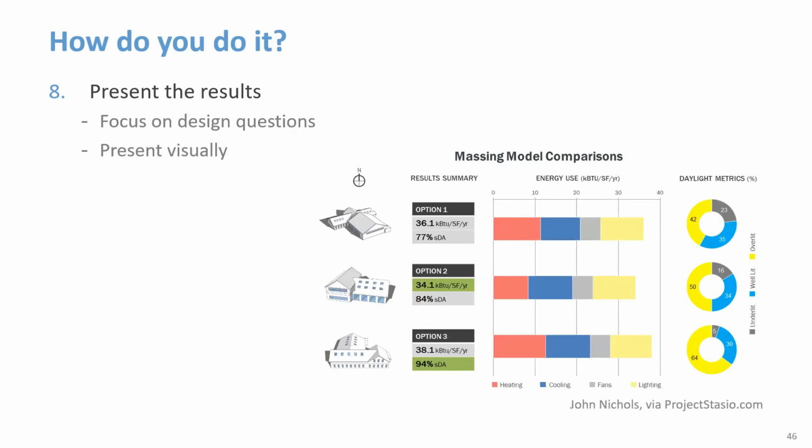The next to the last step is presenting the results of the analysis. When presenting results to owners and design teams, here are 2 recommendations. First, focus on answering design questions rather than on presenting simulation results. And second, present the information visually. Energy modeling results have little value if decision makers cannot quickly understand them.